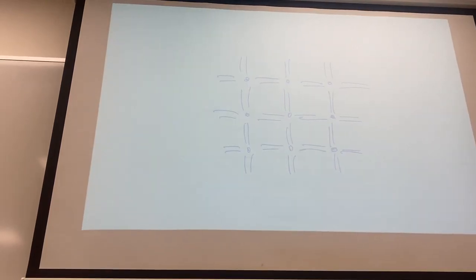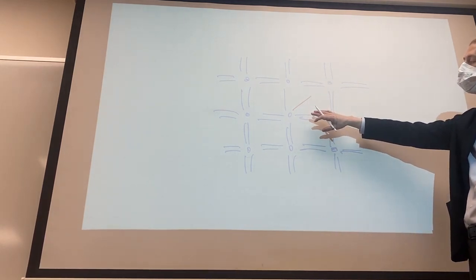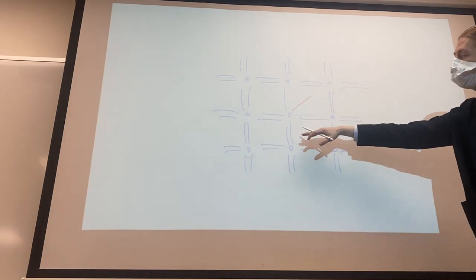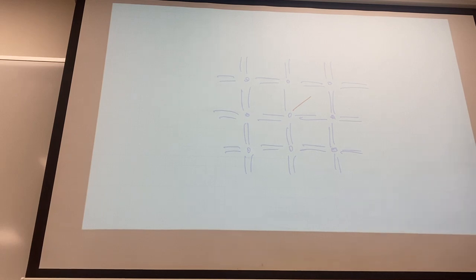And lastly, speaking of thermal equilibrium, intrinsic silicon at any temperature that's not 0 Kelvin has some of this stuff happening, just random, just bubbling away. So randomly, intrinsic silicon will end up with an electron that pops out of its covalent bond and is free to move about the lattice. So we end up with an electron hole pair. They get produced and are just sitting locally, and randomly they should recombine, but also randomly they separate, and on average there's a hairy formula that I'll write in a minute that tells you about how many of these per unit density happen randomly at a given temperature.